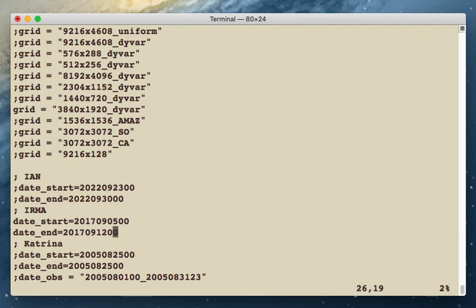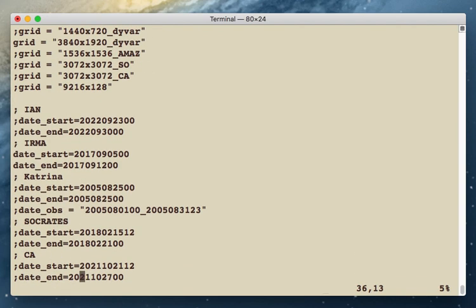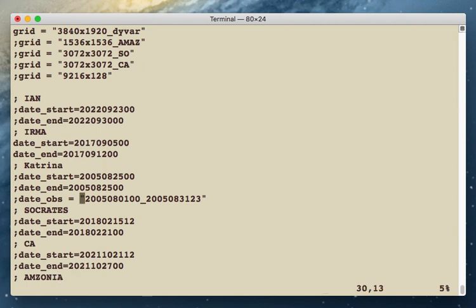If you want to specify only one time, only initial SST, in that case your end date should be the same as the start date. That's all it takes. The advantage of specifying just one time step is that the model does not care about the timestamp in that data, so it will read it regardless of its actual time. That's the only difference.